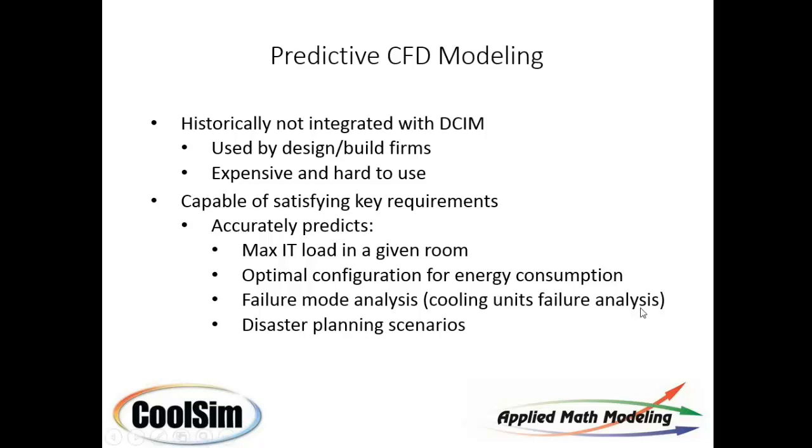The other thing CFD is very useful for is disaster planning, failure mode and disaster planning. What happens if something fails? That's an important thing to know before it occurs. These units have to be maintained. They often have to go down for maintenance, the cooling units. And if people don't know what's going to happen under those conditions, they may be in for a surprise.